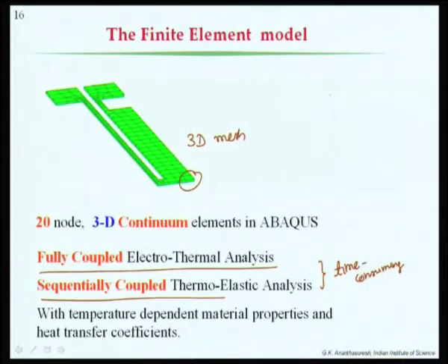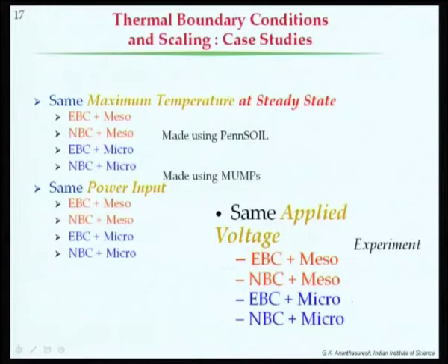First we have to solve the electrical problem, then the thermal problem, and then the elastic problem. When you take temperature dependent material properties, it gets even more time consuming to simulate this kind of structure. A small case study can be done where we try out different boundary conditions.